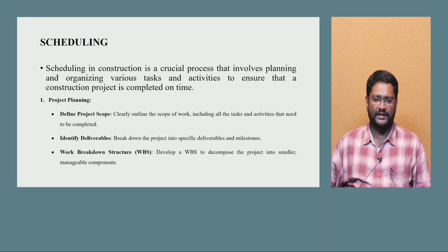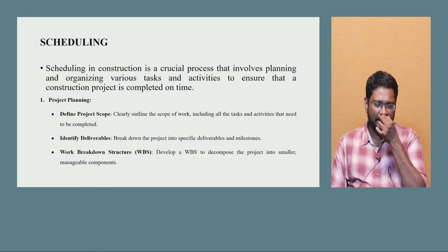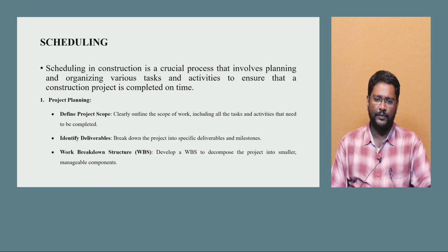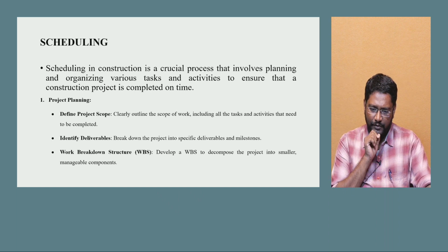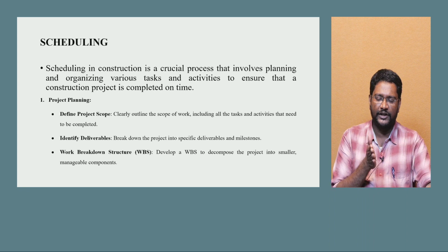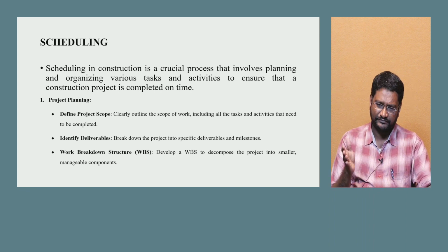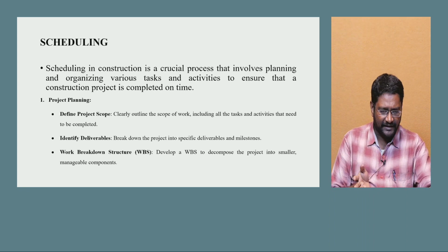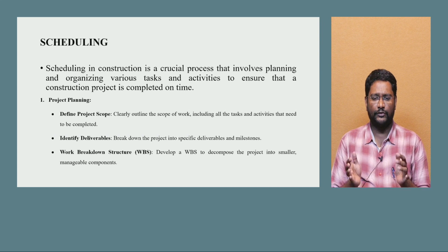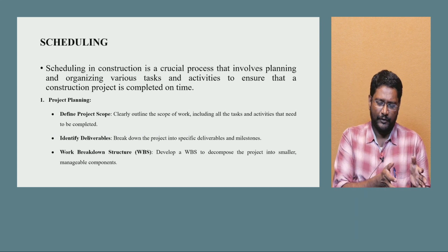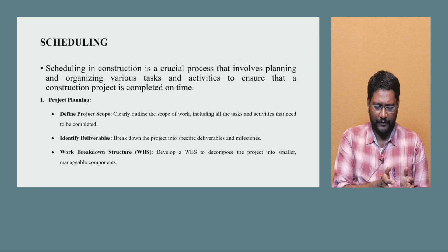Okay, work breakdown structure. WBS is nothing but a work breakdown structure. Develop a WBS to decompose the project into smaller and manageable components. So what is a manageable component that has to be managed? For example, in the same previous example, assume there are 100 piles. We have to group them into 10 or 15 piles per group, and that has to be one breakdown.